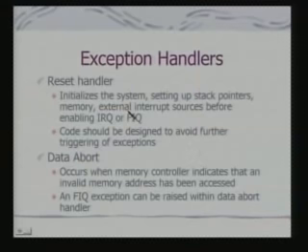You also have to initialize stack pointers, because until you set up the stack, you cannot really process the interrupts, since you might need to save the registers into the stack. The reset handler code should be designed in such a way that no other exceptions occur or get triggered during execution of this code, because they may not be correctly serviced, as you have not set up the vector tables or the stack pointers correctly. So all these things are to be done by the reset handler.